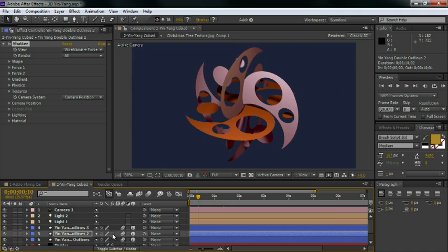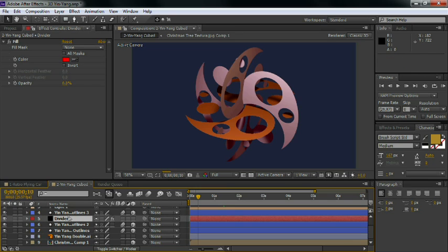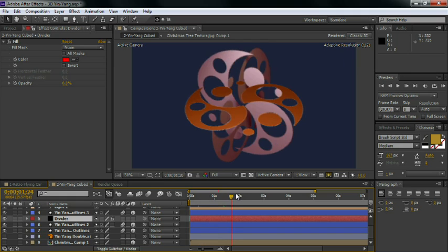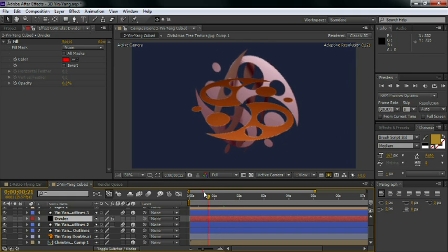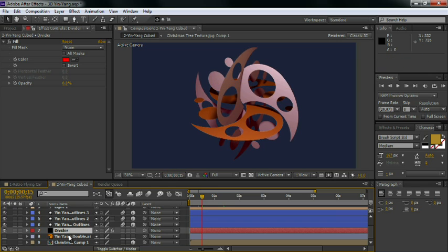Also, if a stack of 3D layers is interrupted with a 2D layer, the result is it acts as a sort of divider. That is, anything above the 2D layer will be rendered into a scene that appears above the 3D elements that are below the 2D layer. This can be very useful when you know it's there, and very confusing when you don't.